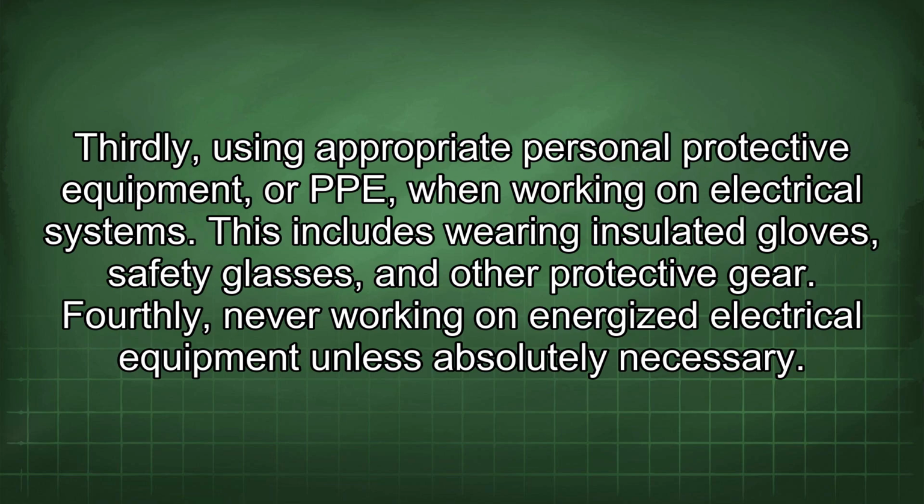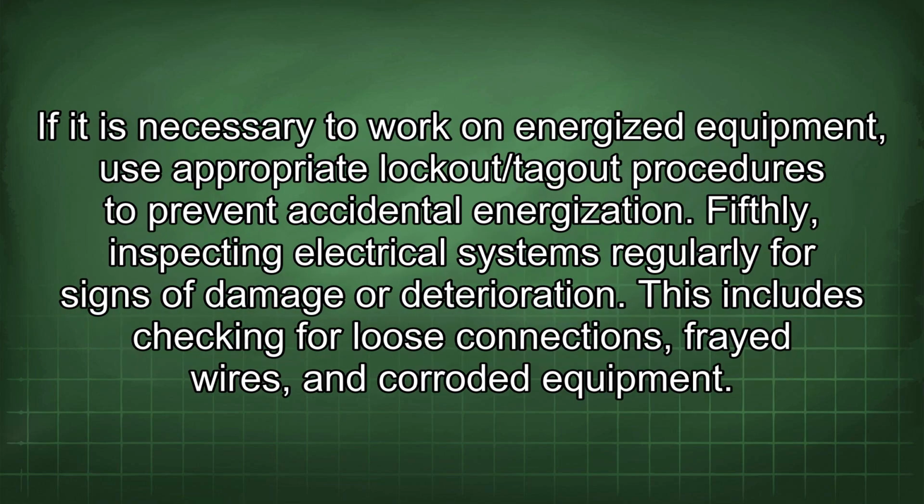Fourthly, never working on energized electrical equipment unless absolutely necessary. If it is necessary to work on energized equipment, use appropriate lockout/tagout procedures to prevent accidental energization. Fifthly, inspecting electrical systems regularly for signs of damage or deterioration. This includes checking for loose connections, frayed wires, and corroded equipment.